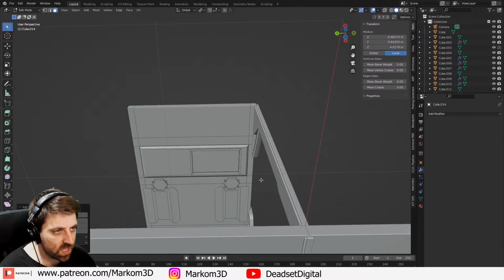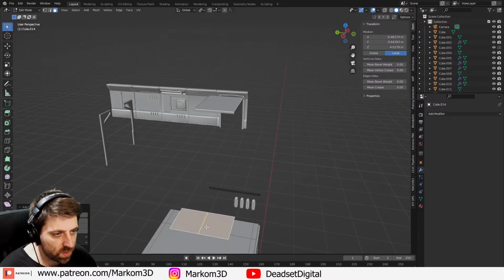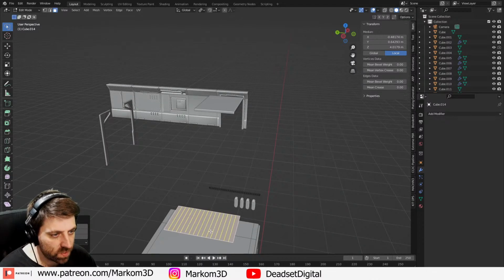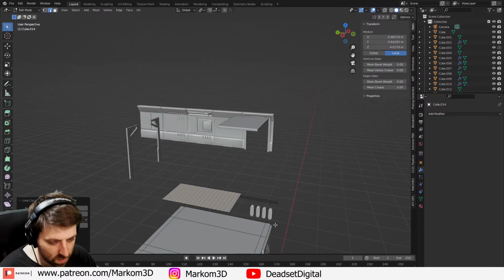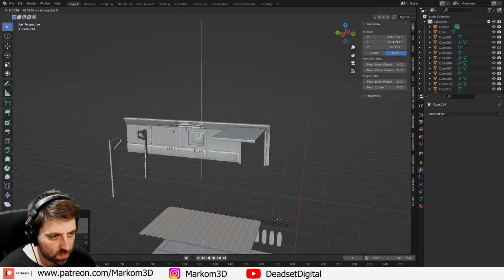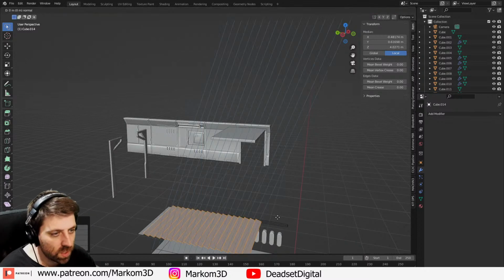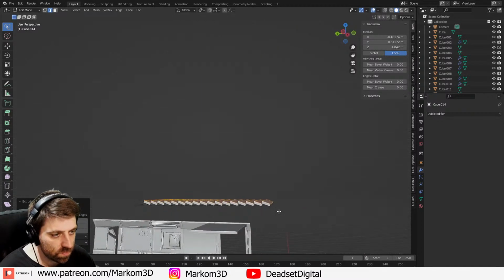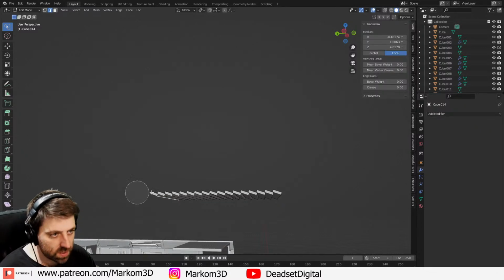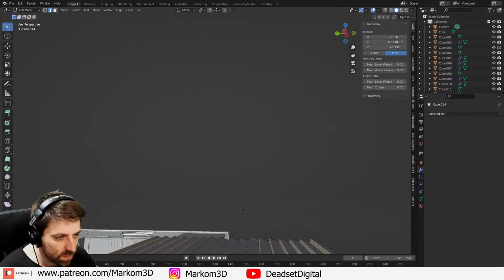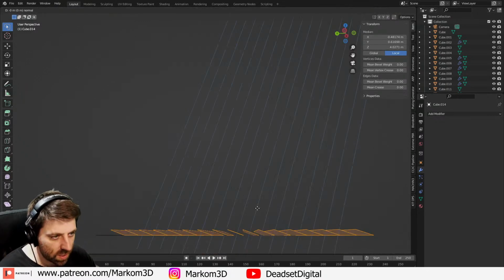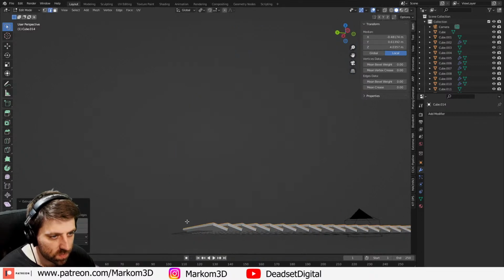From here, Shift D to the Z. I'm going to go scale, put a bunch of edge loops in there, V to rip, GZ, Control L, E to extrude. Inset, delete that. Let's go C. Ah, too much. E to extrude, just a little bit.